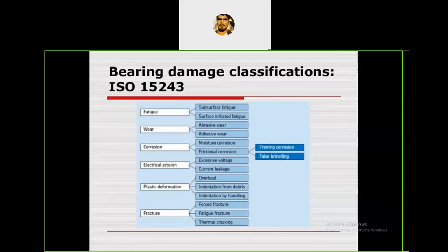The next type of wear is corrosion wear, where a reaction takes place and forms a rust layer. Next is contact fatigue wear. It is a cyclic stress induced in the two surfaces, and it causes the wear. And the last type is electrocorrosion, where because of the current, it destroys the ions or atoms in the surfaces. It causes the wear. That wear is called electrocorrosion wear. Clear?